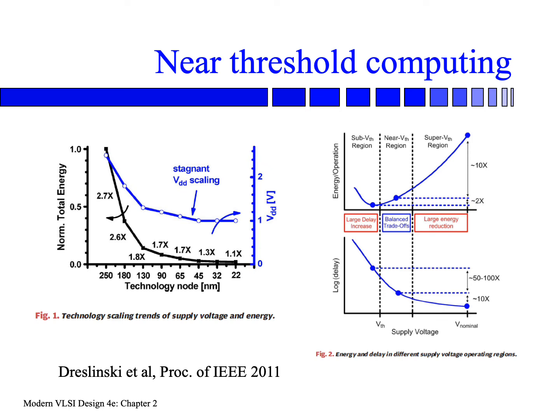Another one is that the chip becomes much slower, because if you use less current, it will take a longer time to discharge the load of this device, which is typically capacitance. Suppose the device capacitance does not change, then you have to take a longer time to charge or discharge. So you can see that the delay goes up a lot. This is even in log scale.